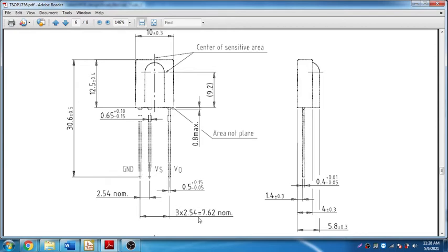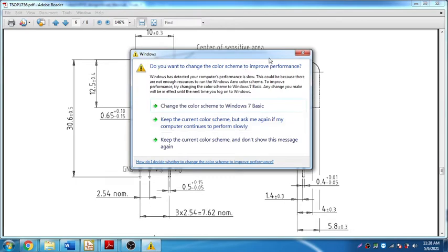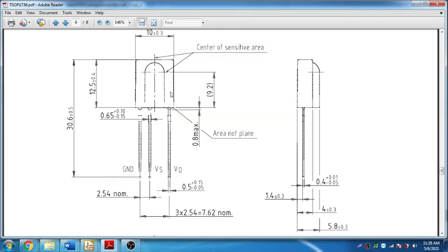That makes sense. So it indicates that VS to VD, this pin to this pin, the gap is around, I think, 5.08 mm, if I am not wrong, 2.54 into 2. So 5.08 mm. That detail is enough for us. We are not worried about the vertical placement of this, but if you are interested, you can go through this. It is 12 mm roughly and 30 mm, 3 centimeters from the pin. Anyway, that doesn't matter much.